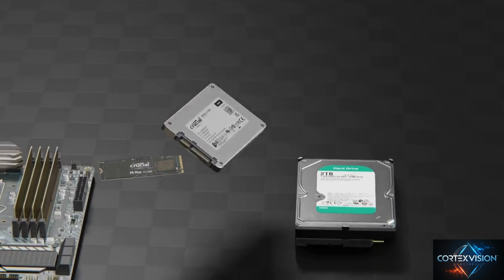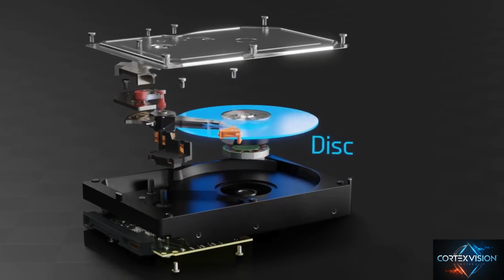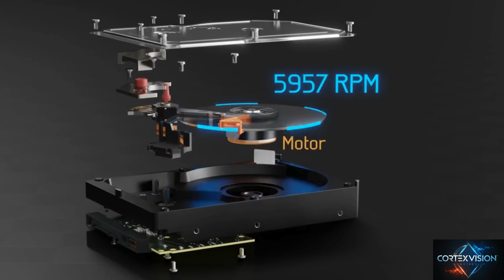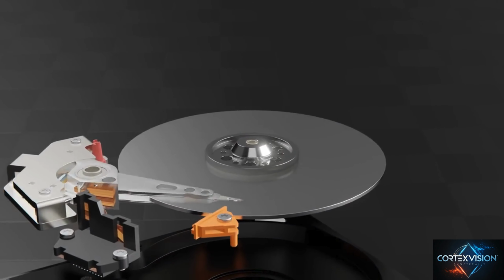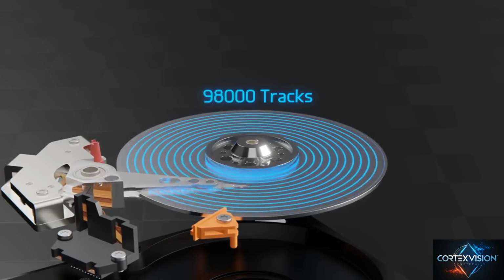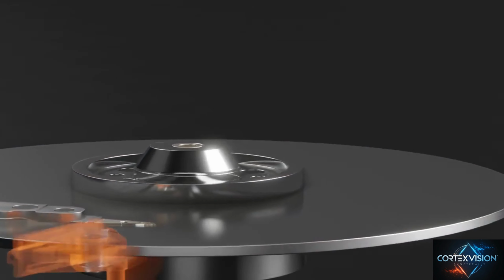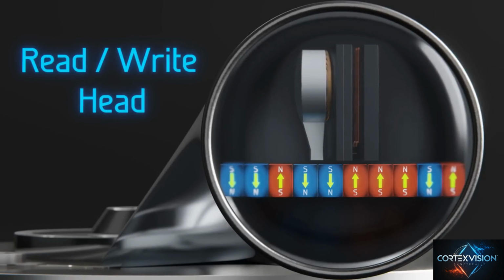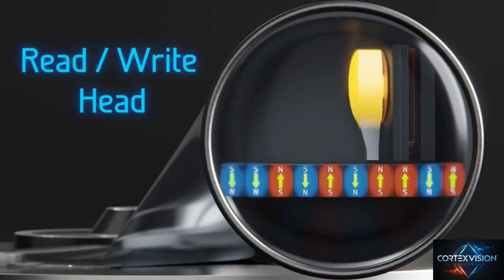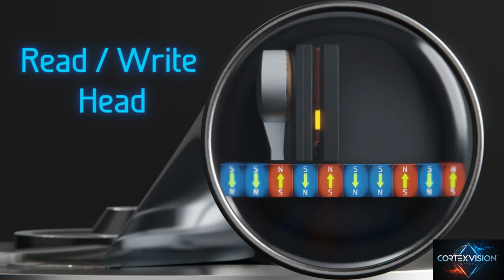Let's move on and dissect the hard disk drive. Here we have a disk mounted to a spindle with a motor that rotates the disk at thousands of RPM. A read-write head moves across the disk in order to access a single track out of 500,000 other data tracks. Let's zoom in on the read-write head. The write head changes the direction of localized magnetic domains in a small layer on the disk, whereas the read head senses these changes in magnetic domains.